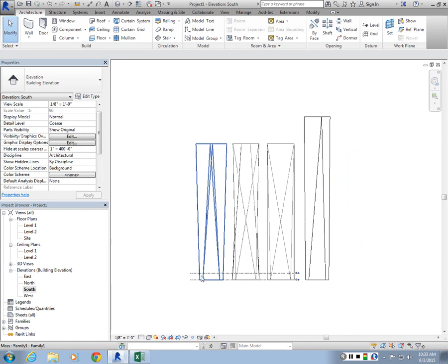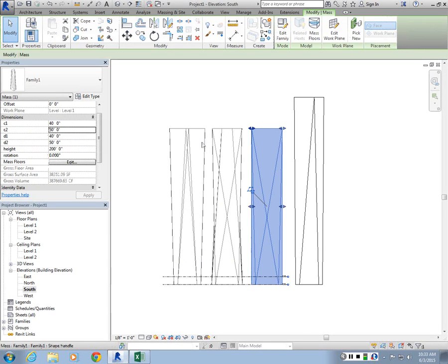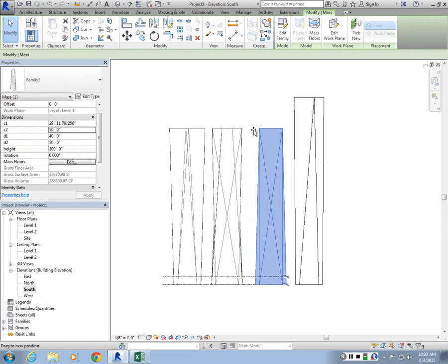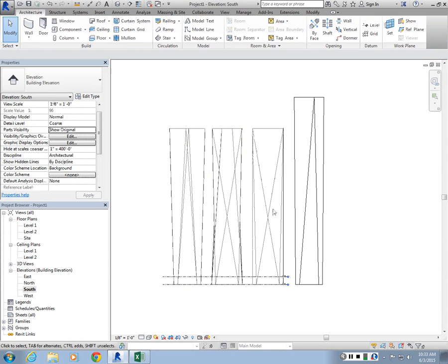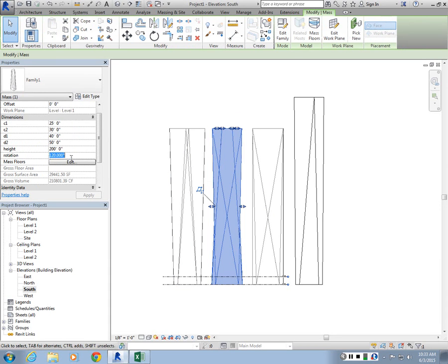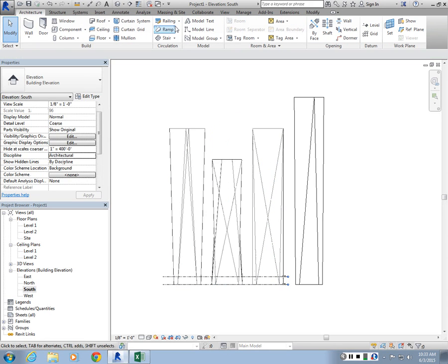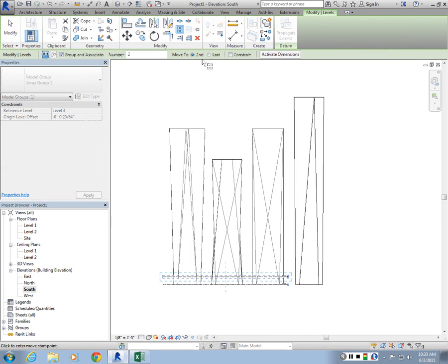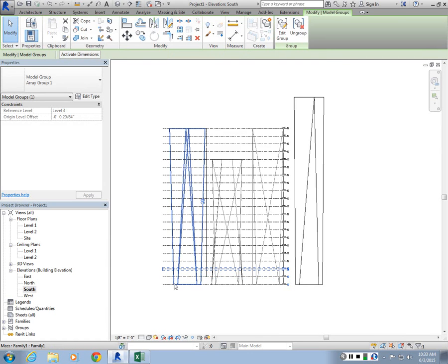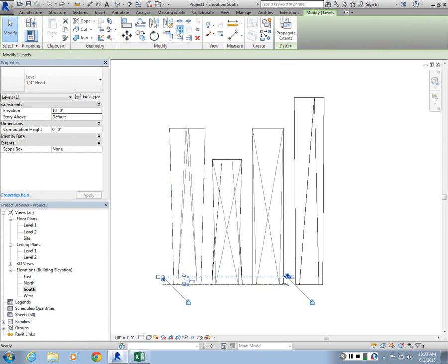And you can go to an elevation view. You can also manually play around with some of these values using these handles. But again, you will get decimals, right? Because you're doing a rounded flex. Let me change the heights. So let's make this 160. So maybe I have something like this. And I'm going to go choose one of the levels. Again, you can create an array. I'm going to create 20 more floors. Actually, let's do 25 array.